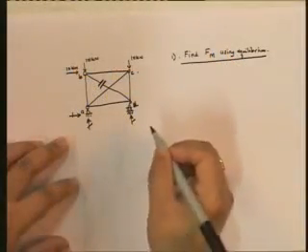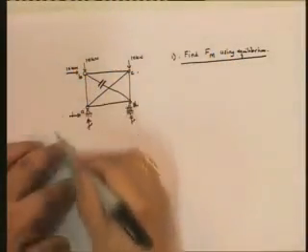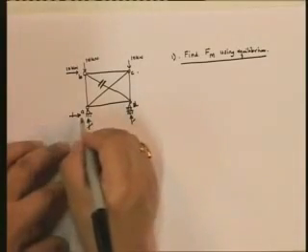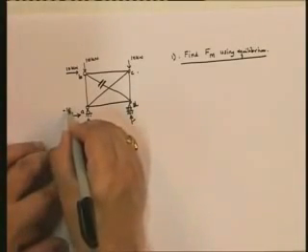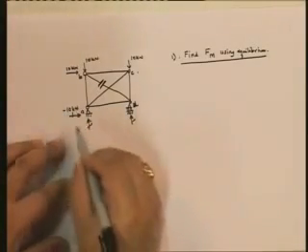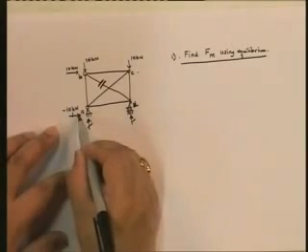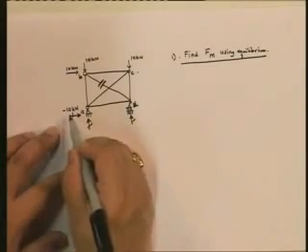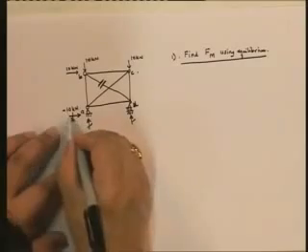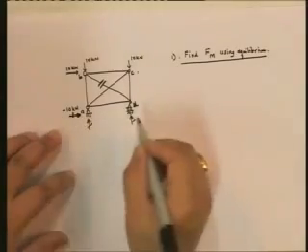However, in this particular case, I will actually go about solving. I'll go through the steps without writing them down. First and foremost, these are the unknown reactions. So let us do sigma Fx equal to 0 for the entire structure. That gives me that this is equal to minus 10. In other words, the direction that I am showing is actually in the opposite direction, 10. So I am putting down minus 10 because I have shown it in this direction.